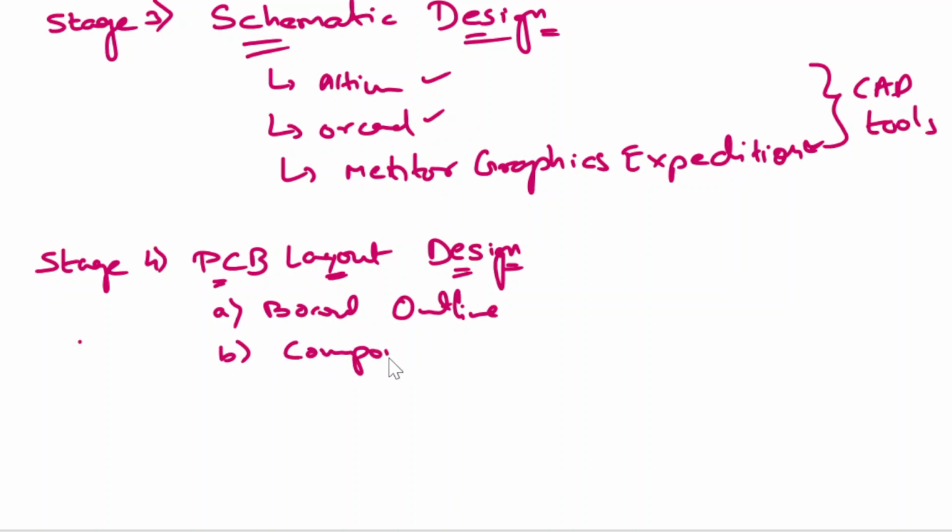Automatic component placement, right? Not automatic, there's engineering behind this. Some tools I have seen, if you upload the BOM of the schematic, it will import. I'll tell you in short, and you're going to discuss that in more detail in going forward classes. See, normally when you import, all these ICs or components are put randomly in the layout in the tool. Then what you do is bring them near to each other, so that it is as per your requirements.